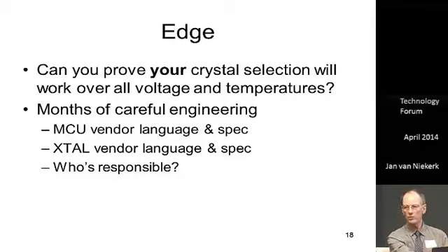And so when you are going to put in a crystal, make sure that you talk to the vendor of the CPU and to the crystal maker, and make 100% sure that if you're not the expert, somebody who knows what's going on signs off on that. I'm going to use this crystal with this microcontroller. So just be aware of that.